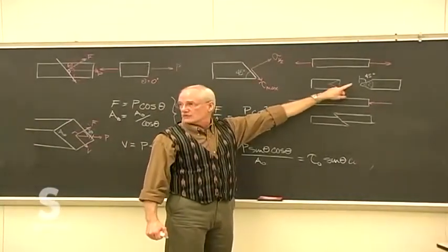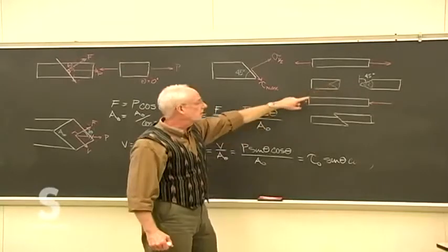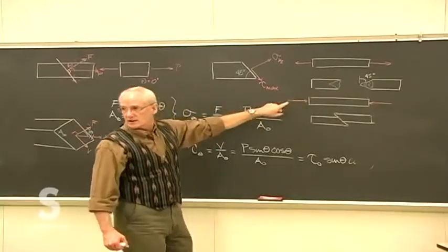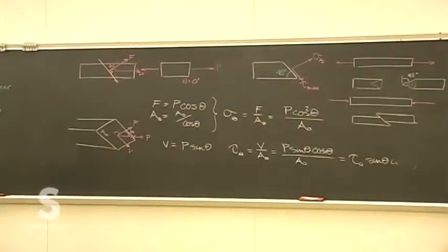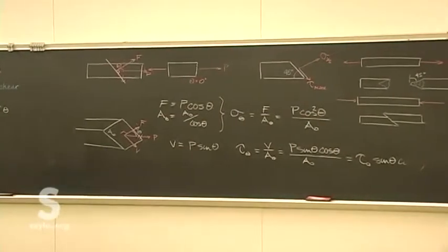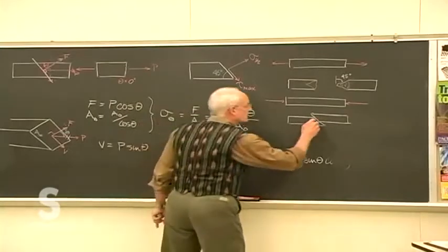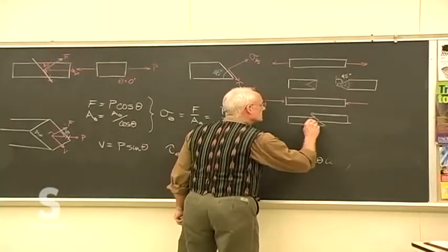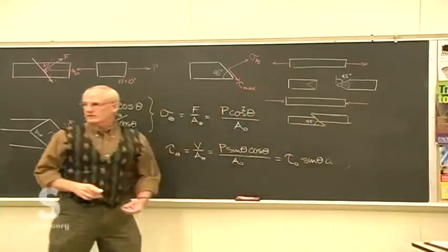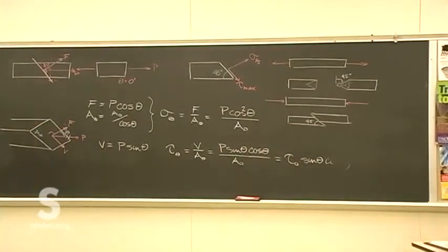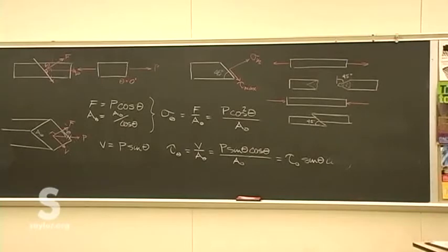see sort of this type of surface forming, and I've also got a piece of wood in compression to failure, and you'll see that it splits in very much this type of way, and this is fairly close to that 45 degrees. Of course, this assumes a completely homogeneous material, which is not the case naturally.